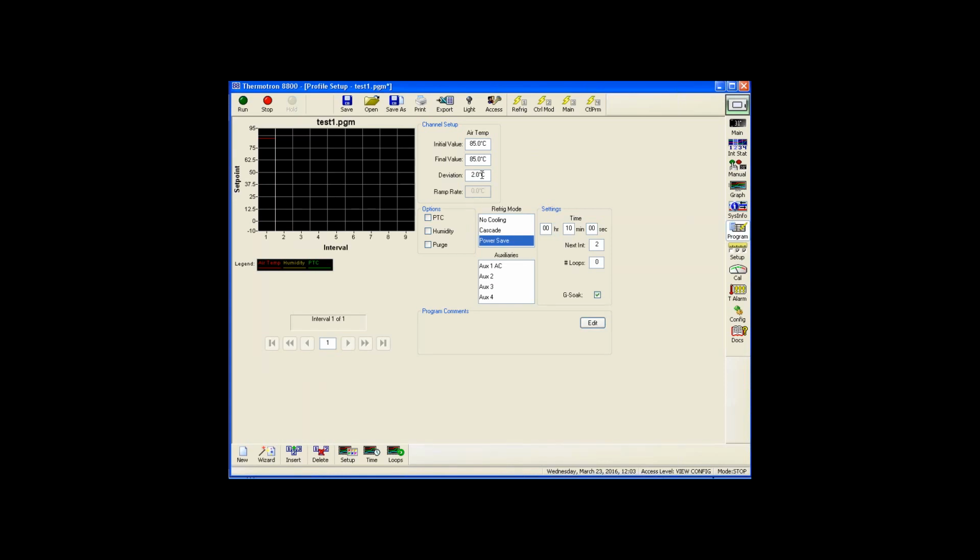If the temperature drifts out for some reason, the test is just going to keep on running, and it's up to you as a user to go into the graph and look at the test to ensure it was running. We had a particular customer. They were running a 2,000-hour test at 85, and the water supply to the humidity was disrupted. So after like 3 hours, it went from 85 to like 85.2% because there was no longer water going to the system. And at the end of the 2,000 hours, when they went to check on it, they realized it had run out of water right in the beginning, and they came to us and asked us for a solution.